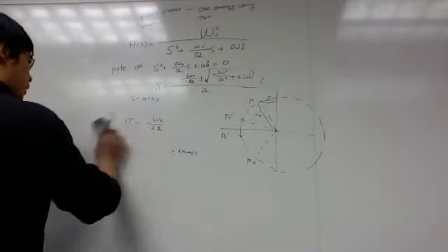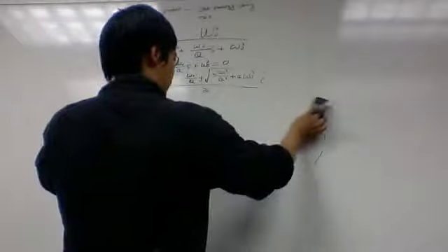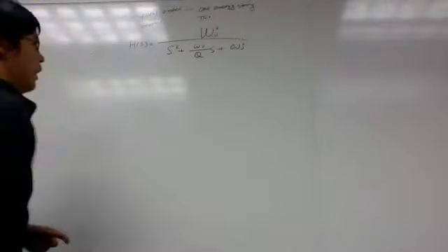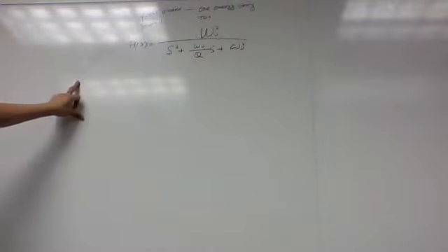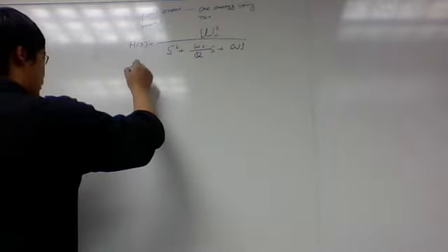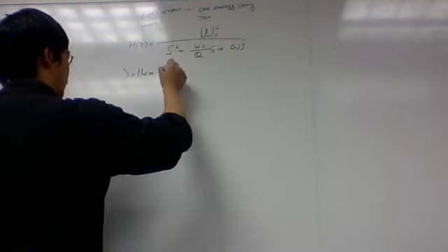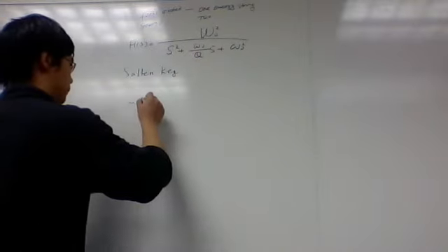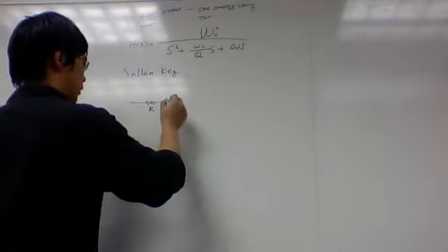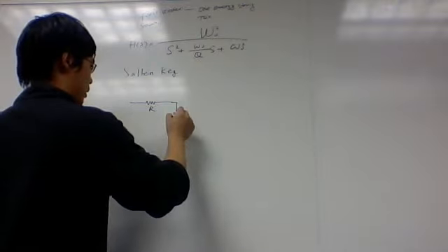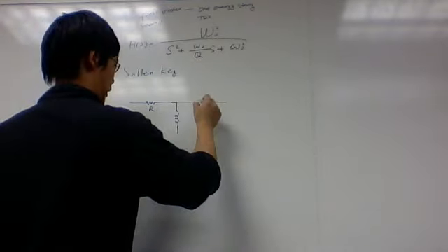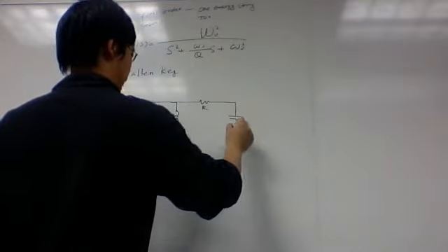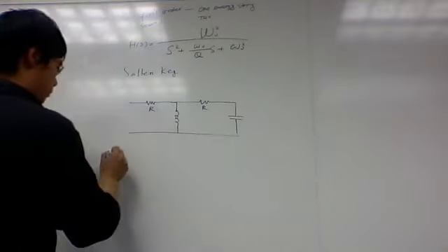So we need to see how we can actually realize this function, right? We know we have to build something like this for the second order one. We have studied something called Sallen-Key. It's one implementation. Basically what we have is R, trying to mimic a structure something like this, an R and a C. So it's called a ladder structure.